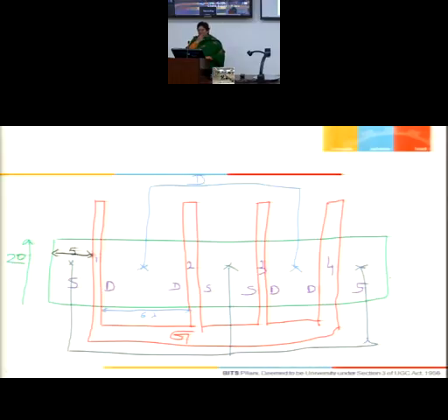So can you compute the total drain area? It is going to be 6 lambda by 20 lambda. Total drain area multiplied by 2, because this is a drain junction, this is drain. Add them together. The two capacitances will add together.